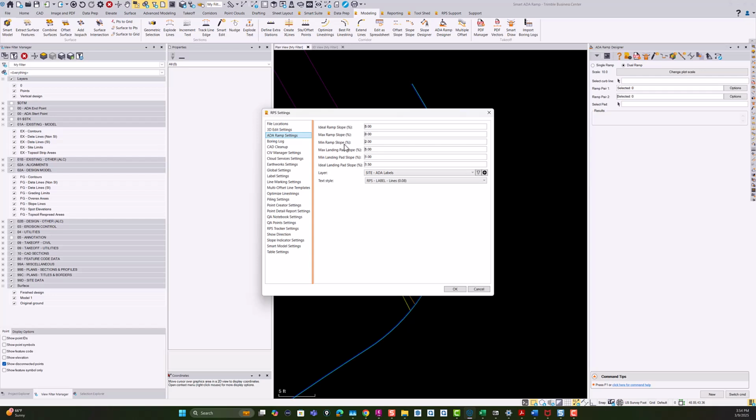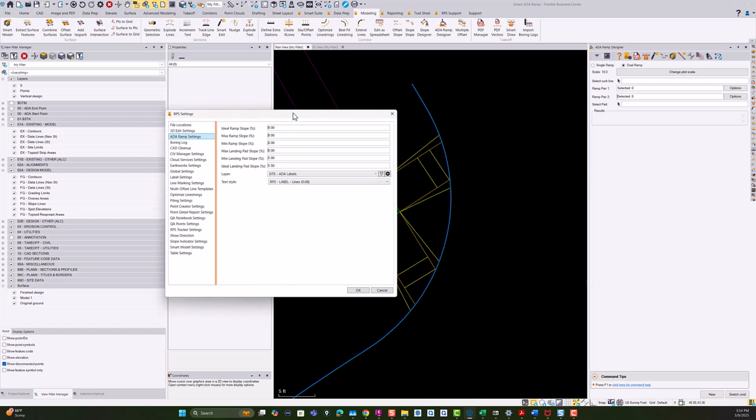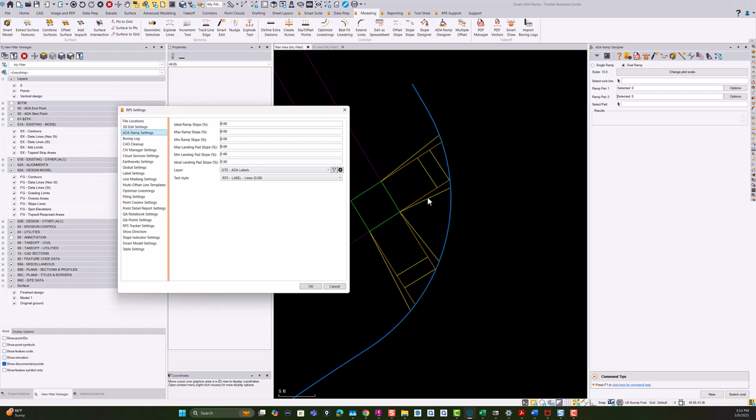So for ramp slopes, which are the slope lines, in this case I'm talking about these lines right here and these two here. These have an ideal slope which is somewhere between a minimum and maximum value. So the minimum slope can be 2%, the maximum slope is 8%, and in an ideal sense, in this case, we've got it set to 5%. That's going to be the starting slope that's used, and then the slopes will be adjusted if the ramp can't be computed correctly. The slopes will be adjusted up or down to adjust the elevations of the points until they all lie within the min-max range.